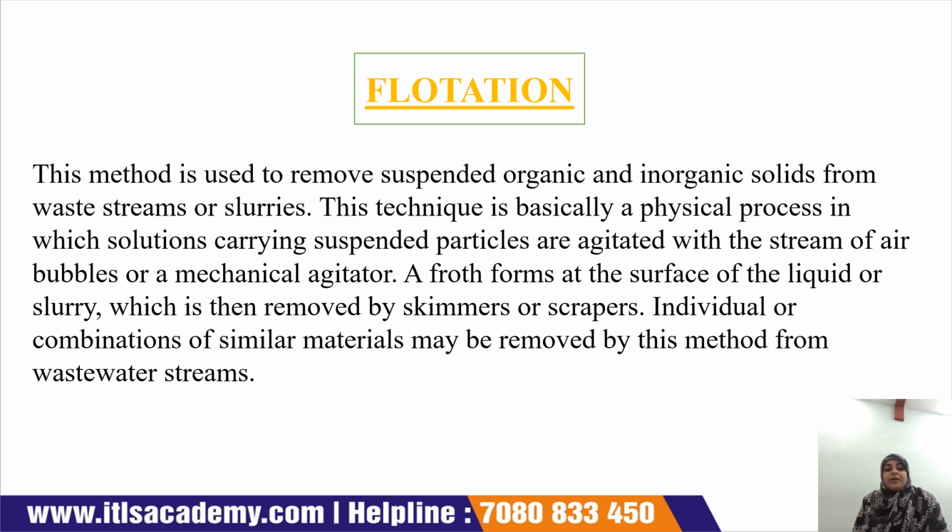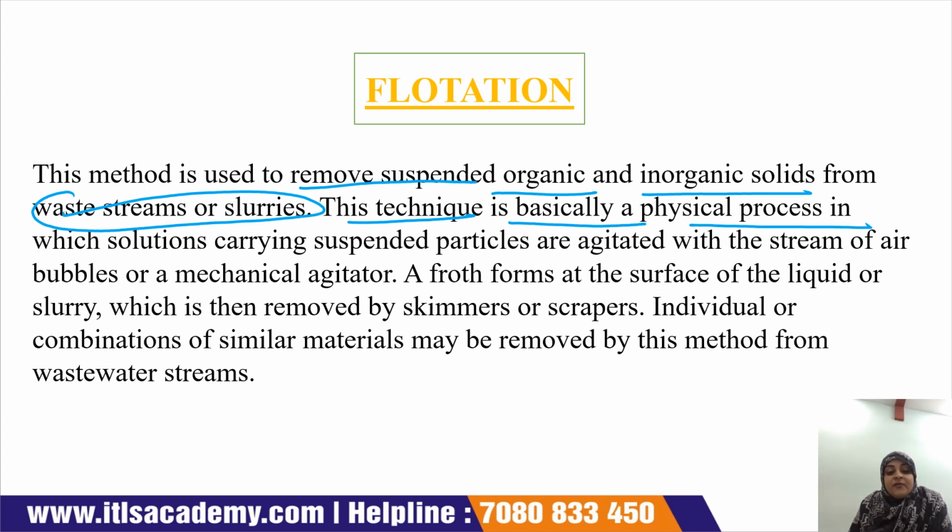Now the next is flotation. The flotation method is used to remove suspended organic and inorganic solids from a waste stream or a slurry. If in a waste stream or a slurry there are some suspended organic or inorganic solids, then we use the flotation method. This technique is basically a physical process in which the solution carrying suspended particles is agitated with a stream of air bubbles or a mechanical agitator.